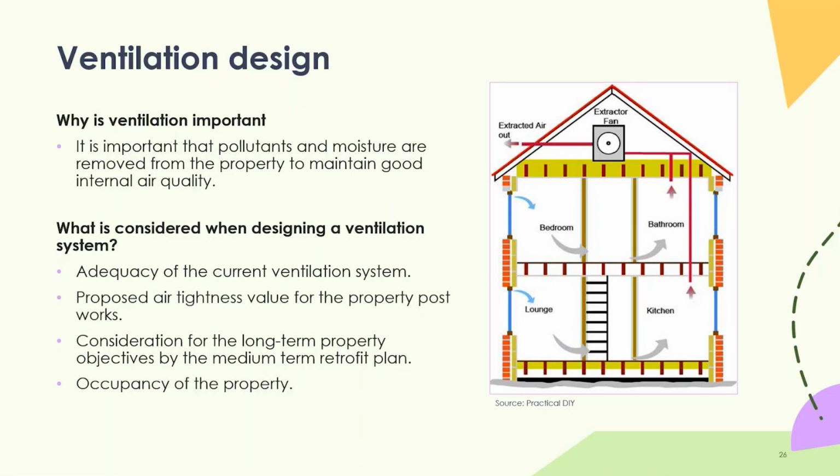Anyway, so in terms of ventilation design, there are a few things to consider. The diagram here is giving a simple picture of the way that a centralised ventilation system might work. So you extract from the bathrooms and kitchens, so damp areas, so you're extracting that damp, moist air, maybe with the kitchen odours, etc., and bathrooms as well.